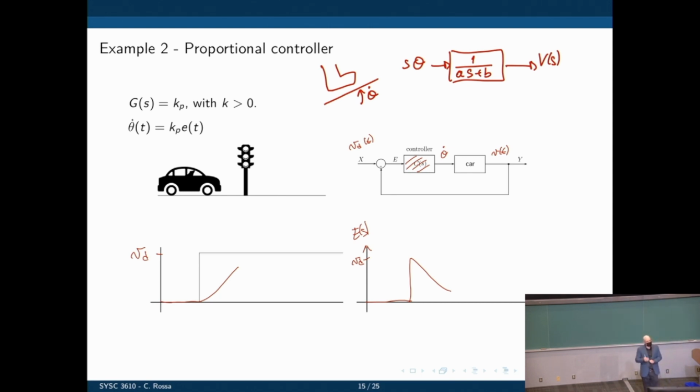And if we reach the desired speed, what happens? We reach the desired speed, the throttle angle is held constant because the speed now is 0. So see, if you're controlling the actual position of the throttle rather than its speed, once you reach the desired speed, what would we do? Just release it, right? But we are actually controlling the speed of the throttle, because once you reach the desired speed, you maintain that at a steady position. Does that make sense?